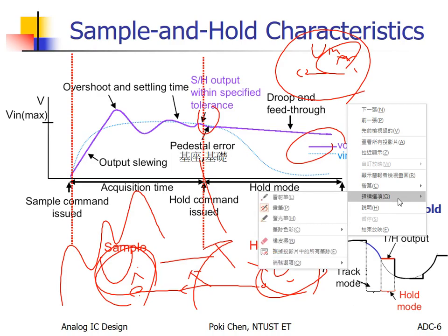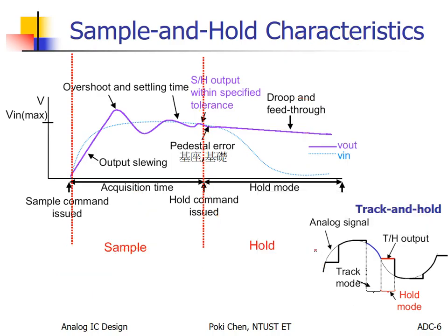But as I told you already last week, for such turning off of the switch, you need to face so-called charge injection and clock feedthrough. Before you turn off the switch, in theory V out and V in can be the same, though it's really hard to say.